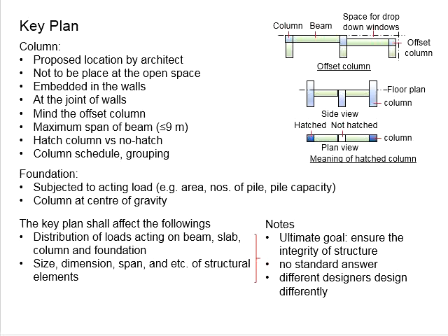And when you try your best to limit the effective depth of the beam, it will not be in the most economical aspect ratio of width versus height. You will encounter a wide beam with short effective depth. This is a very uneconomical design, and you will need a lot of reinforcement bar to strengthen the beam in resisting the bending moment. Wide beams in structures will be the last choice of engineers, not only on the economical aspects. The practical aspects are also a concern.